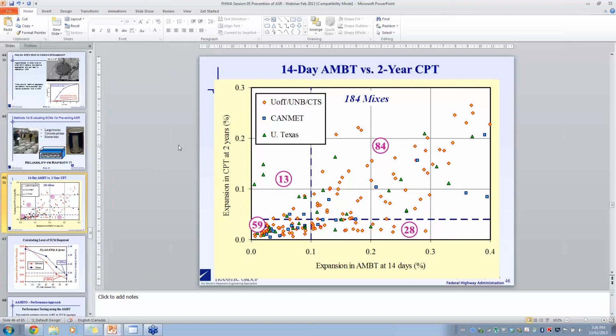If you ended up with very, very coarse, very large aggregate particles in your base, then yes, the future expansion of those could result in heave, I would guess. But generally, if it was a crushed base, I would expect any heave of that base due to continued expansion of the small particles of concrete to be very small, but I think it's something that probably needs investigation.